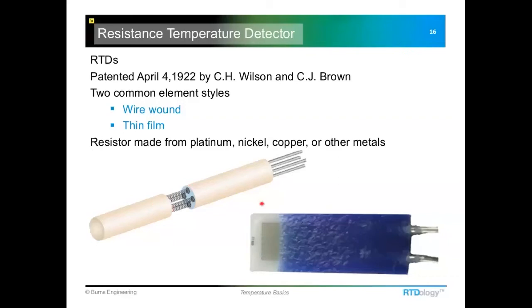The wires here are 7/10 thousandths of an inch in diameter. And then the lead wires out the back, some of the better ones will have a platinum rhodium alloy, so they're a little bit stronger than pure platinum, and those are anywhere from maybe 10 to 15 thousandths in diameter.